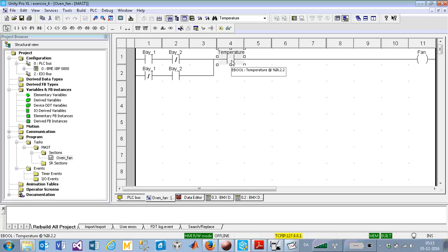And in here I can also emphasize why I suggested during the last lecture that it will be a good idea to start writing down simple sentences before we start doing the hardcore programming. Then after we have written some simple sentences as to what is required from us or what is required from the system, then we can go ahead and translate those requirements into a graph set showing what the program should be doing in seconds. Then that can be put into a program.